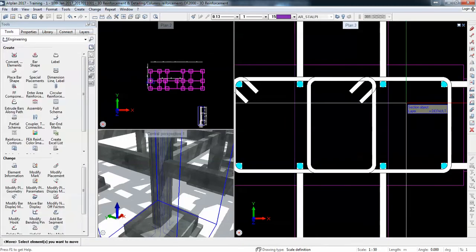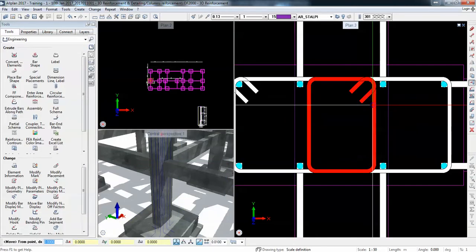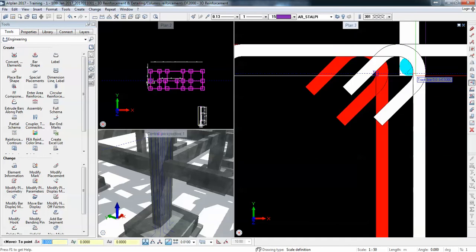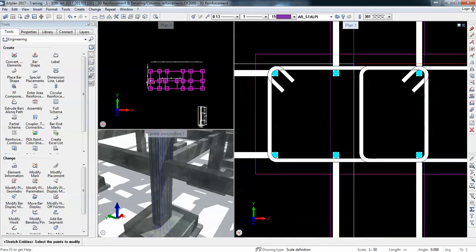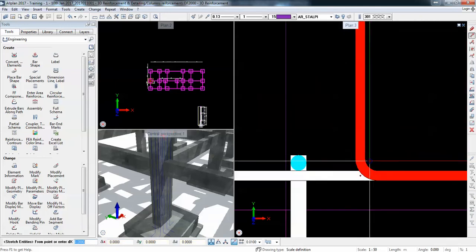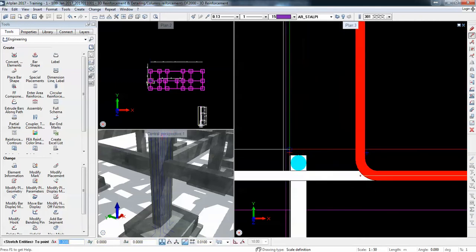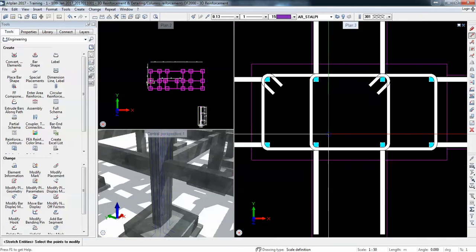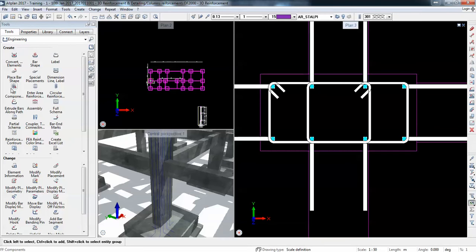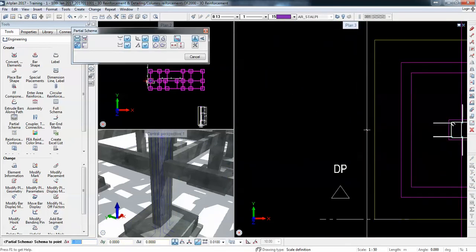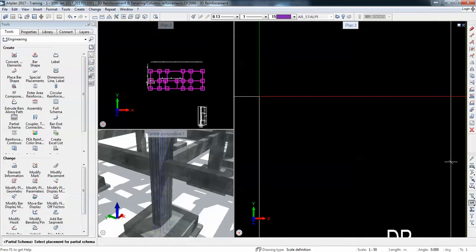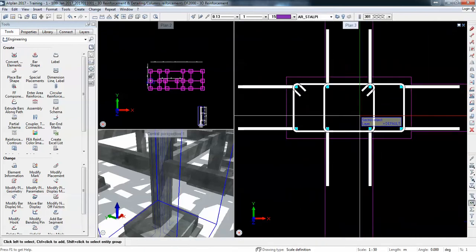So that virtual formwork required a different concrete cover, but I will just do this and then use stretch entities to cover here. If I need to be more precise, it's enough just to pick up the schema and then round a bit, but it's 25, it's round enough for rebar.